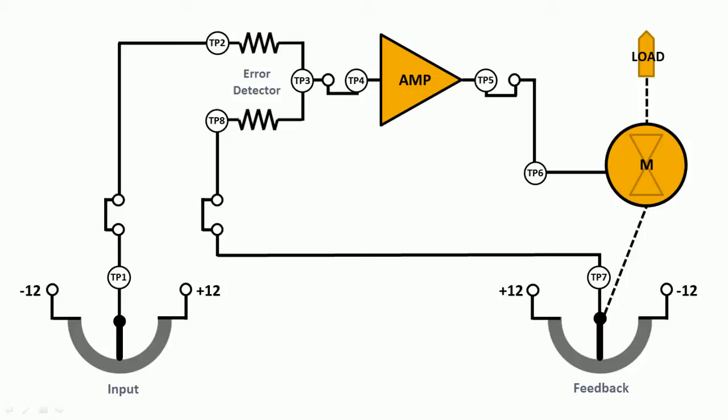In this circuit, the load is moved by a DC motor. In aircraft systems, the load could be moved by AC motors, hydraulic actuators, or pneumatic actuators. This particular motor is powered by a variable negative or positive voltage developed across the input potentiometer. The signal developed across the input potentiometer is sometimes called a demand signal or a command signal.